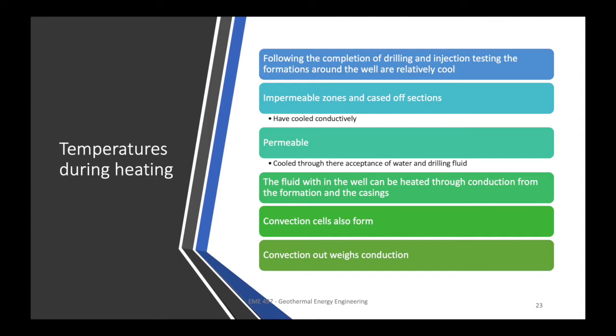Pressure control point. The pressure pivot or control point is important to understanding well behavior. When the well is filled with liquid, the pressure gradient is controlled by the fluid temperature. When there is a single feed zone, pressure in the well at the depth of the feed zone is equal to the pressure of the formation. The pressure profile pivots about the feed depth, and the pivot point identifies the depth.